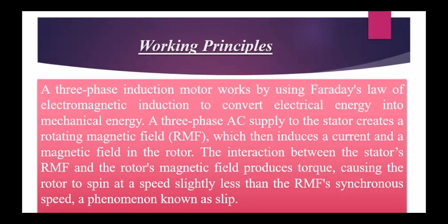A three-phase induction motor works by using Faraday's law of electromagnetic induction to convert electrical energy into mechanical energy. As we know from Faraday's law, when the magnetic field or magnetic flux around a conductor changes, an EMF is produced across the conductor, and electric current is produced in that conductor. On this principle, the induction motor basically works.